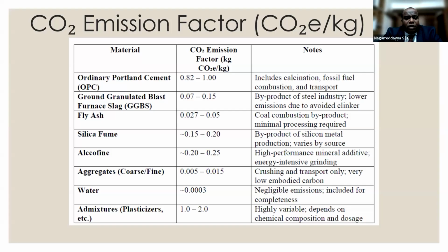If we replace cement with fly ash, we can bring down the carbon emission from 1 kg to 0.05 kg. So these are the remaining factors. Majorly, we are trying to focus on fly ash or ultrafine fly ash and GGBS.